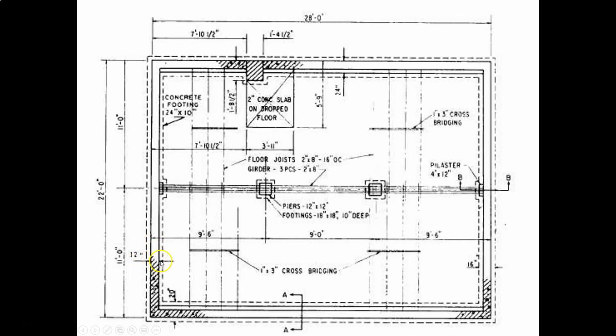So here's the 12-inch wall, so that's good. 20 inches over at this location. So the width of this footing seems to be changing on all sides. 24, 24, 20, and 16. Kind of peculiar. But anyway, it's more about how we're reading the drawing.